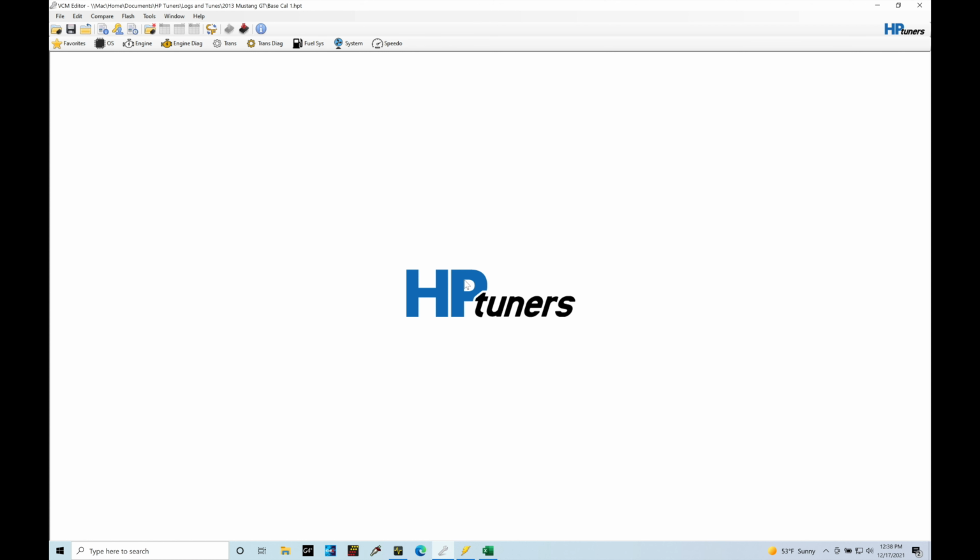Now at part throttle situations, we can use the variable cam control to reduce the pumping losses as the engine is running and improve our fuel economy. So we can use the variable cam control to our advantage to have good idle, good fuel economy, and good power when we're on full throttle conditions. Essentially, we're able to have this high level of tuning capability as long as we're programming the variable cam control properly. That's what we're going to be digging into in this tutorial, taking a look at all the basics of how the variable cam control works.